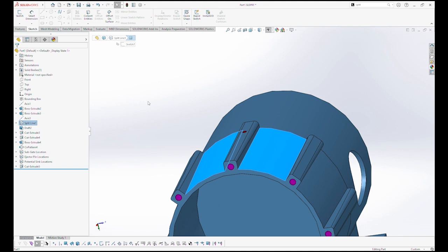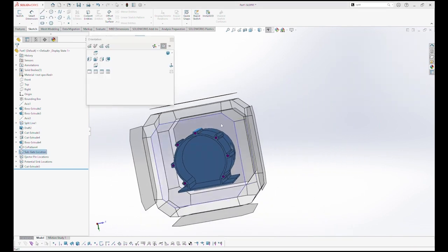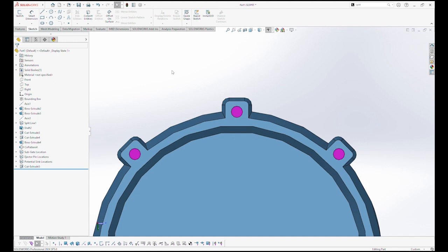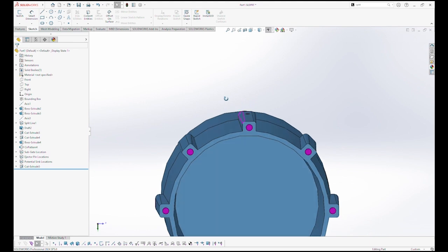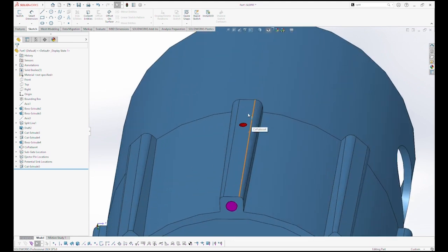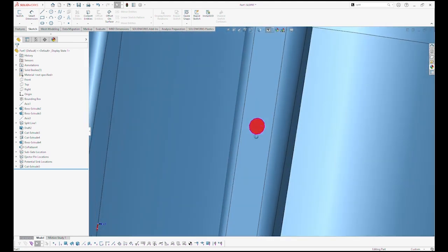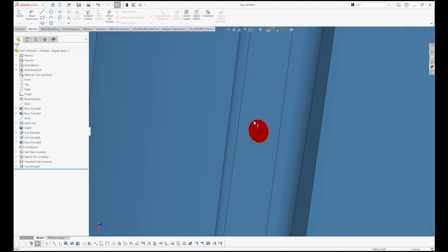But in this particular instance, this surface truly is flat. If you draw a box across the top, that bottom edge of that box shows you that this is a flat surface as opposed to round. And what that provides you is the ability for the gate to shear off cleanly